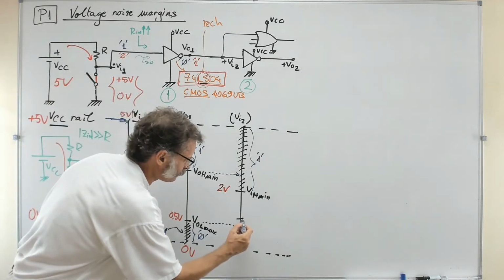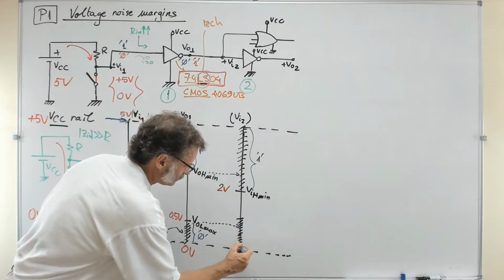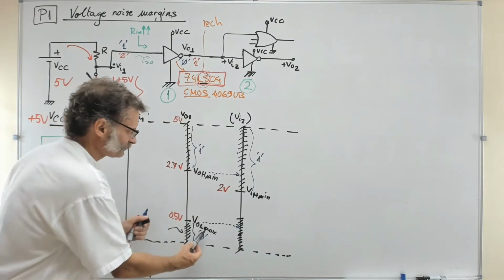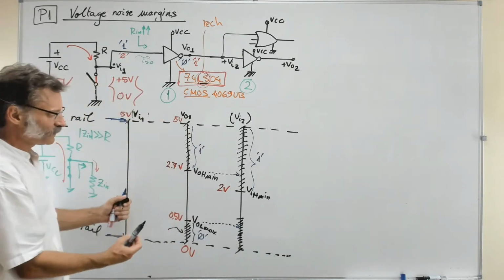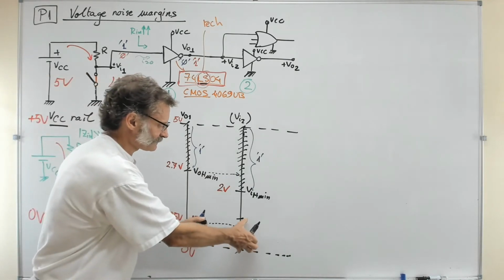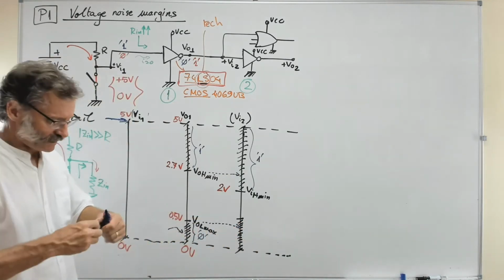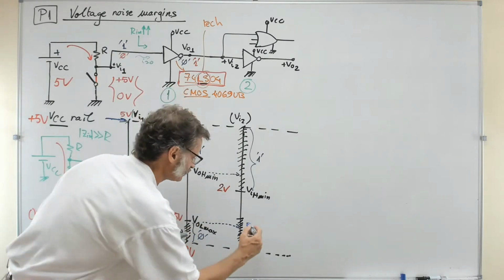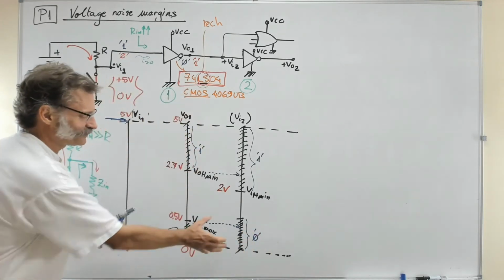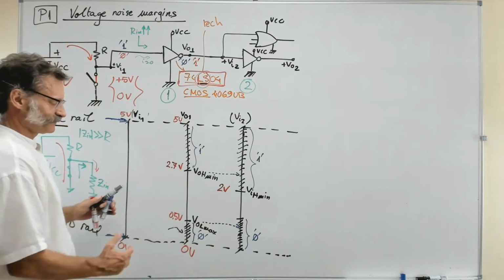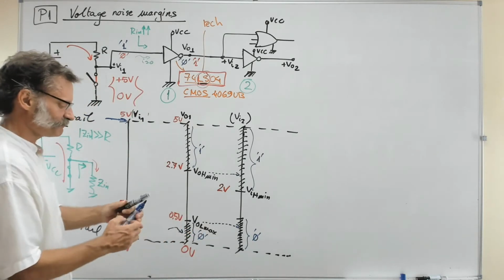You have to cover it like this. The maximum possible level that is understood at the 0, generated by the gate number 1, has to be understood correctly as a 0 as well. So that's the situation, that is what works. Nothing that is not this is going to work. You see, this is what makes the gates compatible.